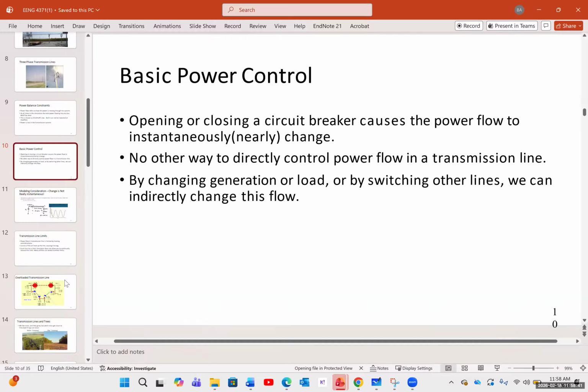If you put too much pressure or high voltage, high current on a transmission line, what happens is first, the transmission line becomes very hot. When it becomes hot, what happens to metal? Expands, and we have the sagging of the lines. If it's too much, it's just going to simply melt. So we have some limitation.